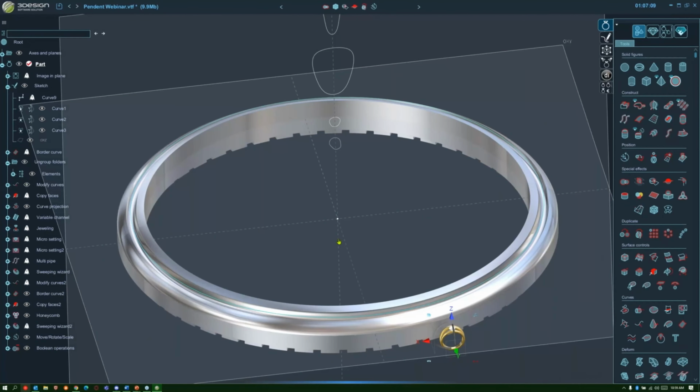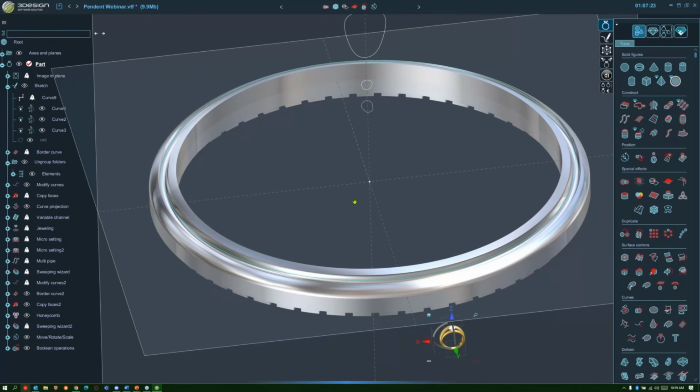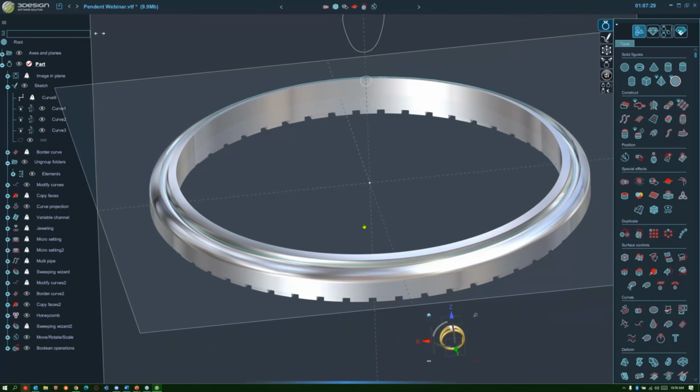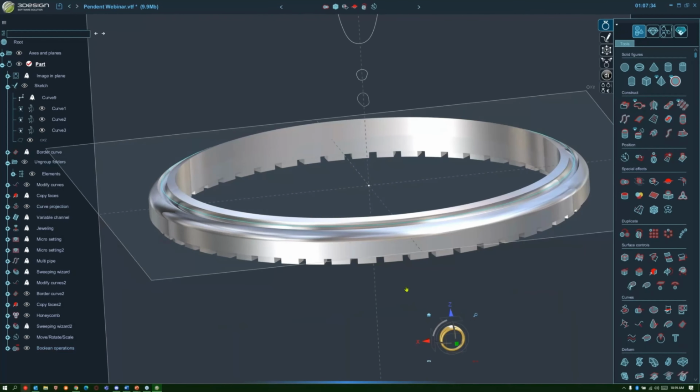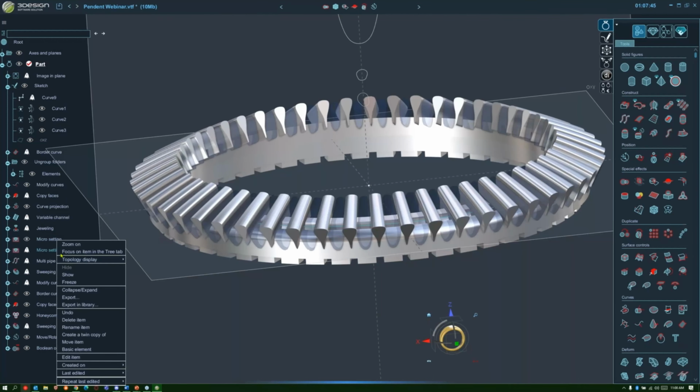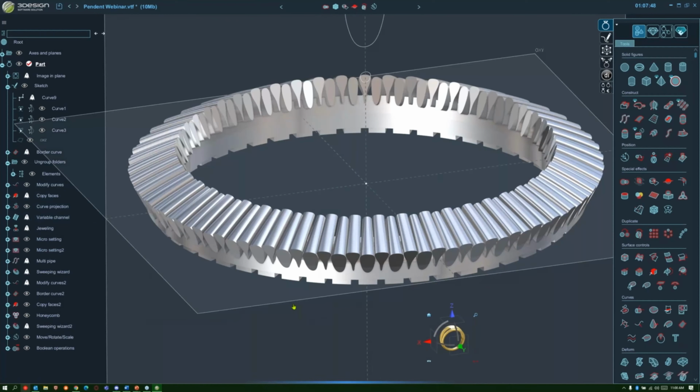Okay, so this is actually good that you got to see the troubleshooting steps, see the different methods to get to the same result. Sometimes, depending on many different factors, like I said, a lot of times it's the seams, it's the projection onto those seams. Just the slightest little differences can make the difference in how those curves behave with different tools. So now we can move on to the rest of our cuts, and hopefully have no more Boolean issues with this one. Let's bring back our micro settings.